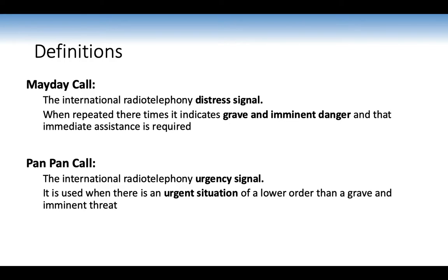if there's a medical emergency, if you're doing a precautionary search and landing, or you found stranded people in the area. And it's really important you know how to do a Mayday call and also a Pan-pan call in case you need to make one, so that you can give ATC the appropriate info and they can give you the help you need. So in the training area, we won't actually be delivering the call to air traffic control. We'll just be delivering over the intercom.